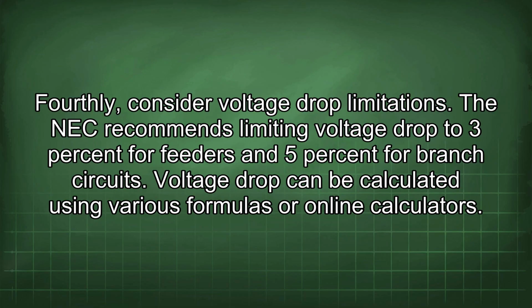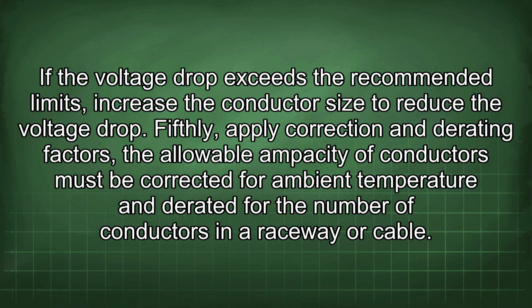Fourthly, consider voltage drop limitations. The NEC recommends limiting voltage drop to 3% for feeders and 5% for branch circuits. Voltage drop can be calculated using various formulas or online calculators. If the voltage drop exceeds the recommended limits, increase the conductor size to reduce the voltage drop.